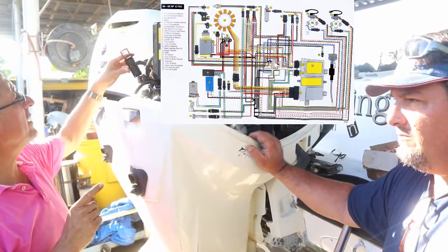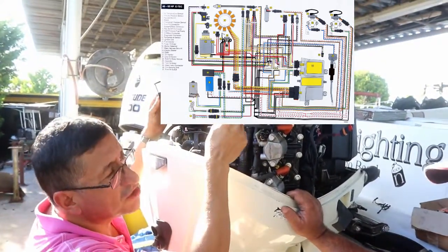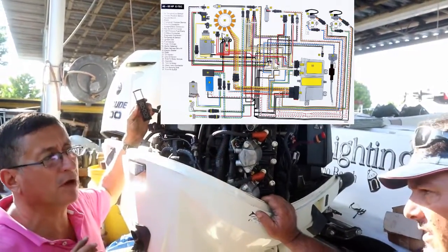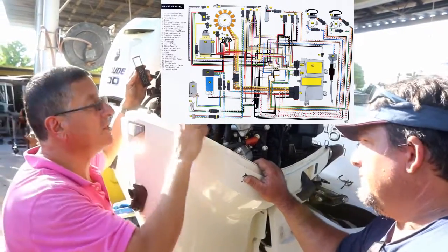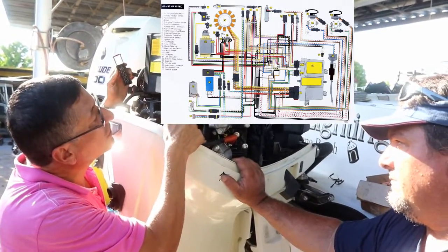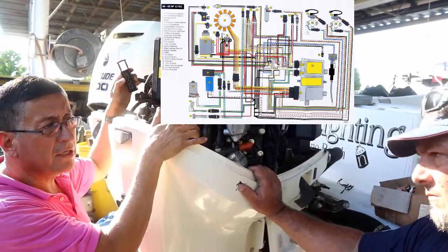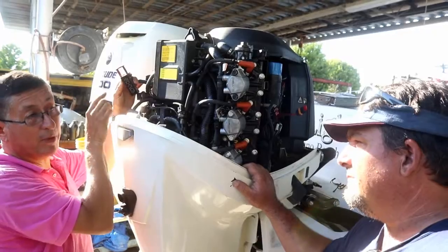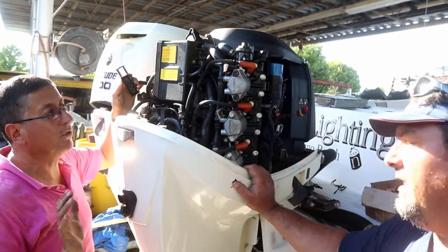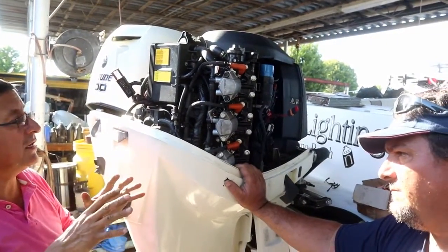If you have the wiring diagram, you can follow each pin according with each injector, each sensor, and each spark plug. That's not complicated. It's identify which cylinder has the problem. Okay, it's cylinder number 2. Let me check the cables for that injector. I identify where the cables are, I check continuity on the wires, and after that I check with my multimeter if I have the output recommended for that element. That's simple. It's exactly the same for the coil of the spark plug. This is the typical troubleshooting for the ignition system.